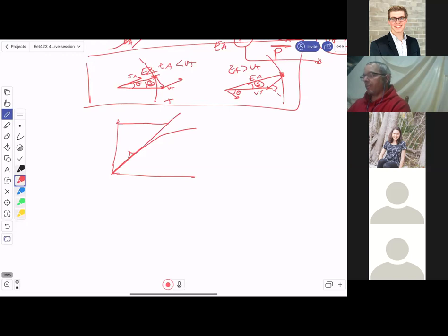So if I give you a field current, but I don't actually give you a curve, you should be able to say, I'm saturated or not. If I draw a slope of this air gap line, any voltage that I have here, let's just say this gives me a field current of 5 amps, I can tell you that that's saturated because the air gap voltage is greater than the voltage on the open circuit characteristic. When the air gap voltage equals the open circuit characteristic, you're in the unsaturated region. So you should be able to tell just by looking at it.